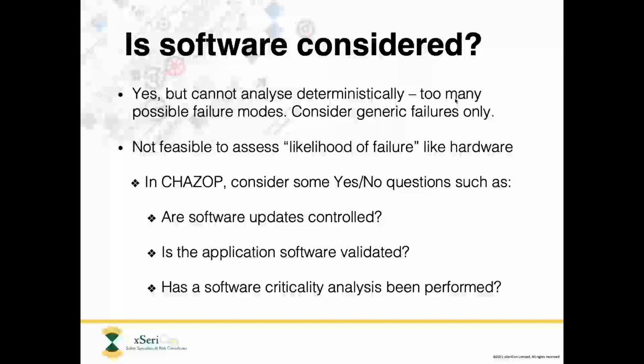Other passive systems built into the controls equipment, such as check valves and relief valves, should still be available, even in the event of a control system failure. There may be backup systems, such as a UPS, uninterruptible power supply, maybe an emergency diesel generator that could kick in or that could be started by the operator. And then there should also be, for the most extreme cases, the ESD system, or safety instrumented system. And as long as it is sufficiently independent from the control system, then that should remain valid as a safeguard for our CHAZOP cases.